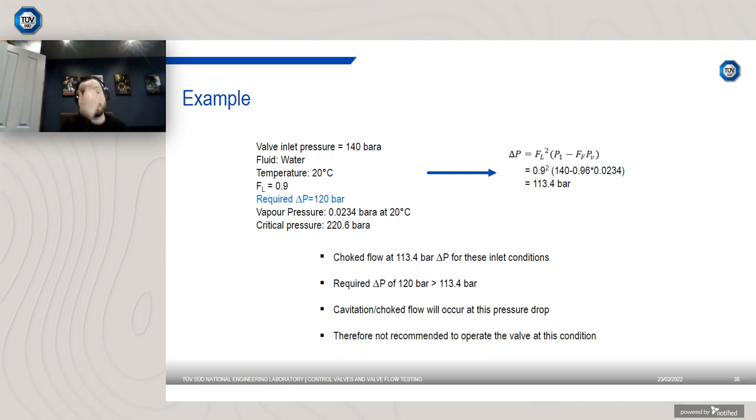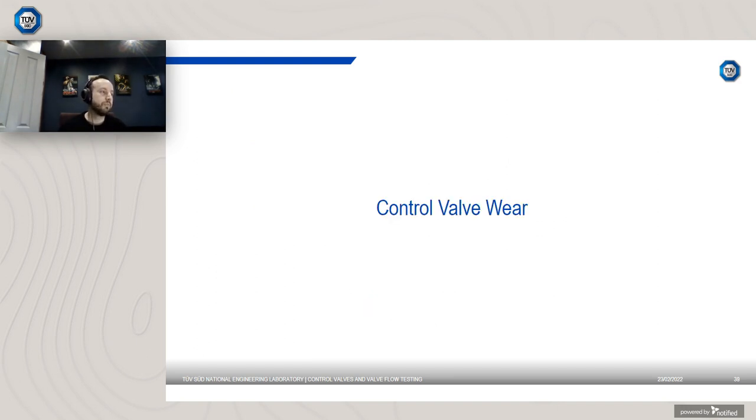And the important thing to remember is without the FL number, or without confidence in the FL number, it's very difficult to actually determine if you're operating at a safe level. So that's valve flow testing. I'm now just going to talk a little bit about control valve wear.